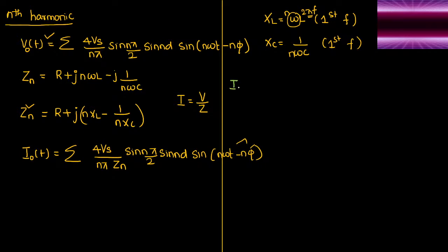Now the fundamental current, I0 of 1. This is what we need now. We need the fundamental current only, and they also told that we need the fundamental RMS current. How do I do this? Now see there. Sorry, this is the nth order harmonic maximum current. Then for the nth order harmonic RMS current, I have to divide this whole value by root 2.